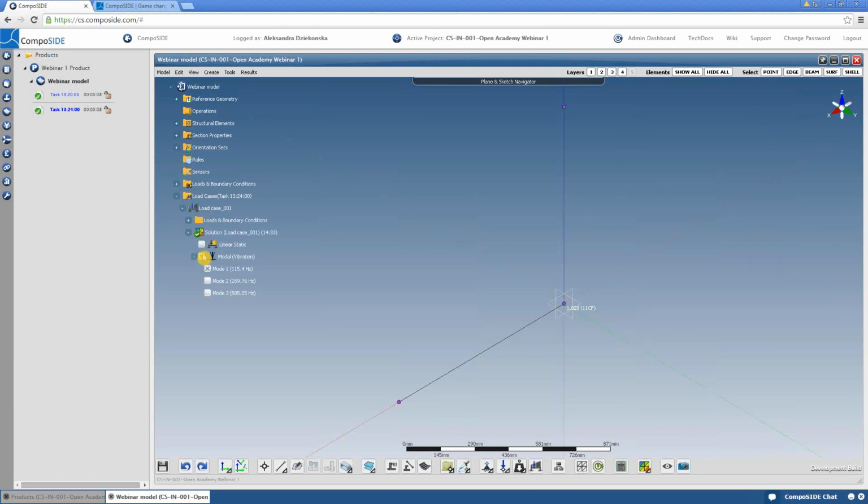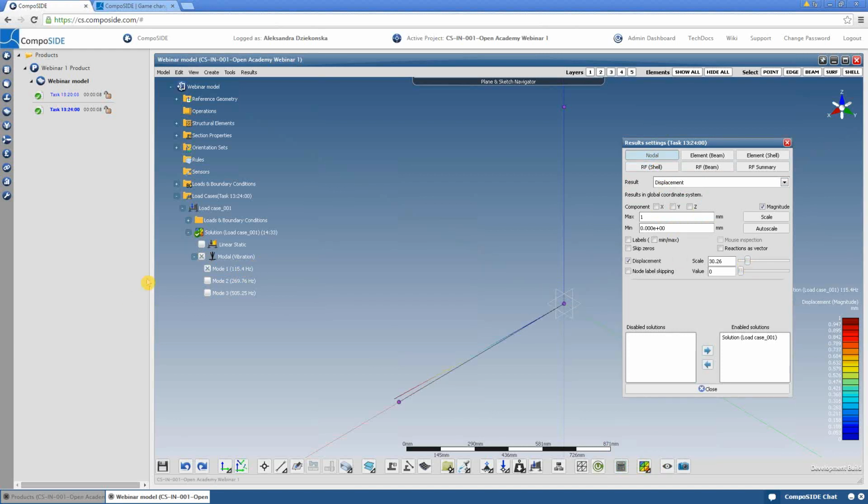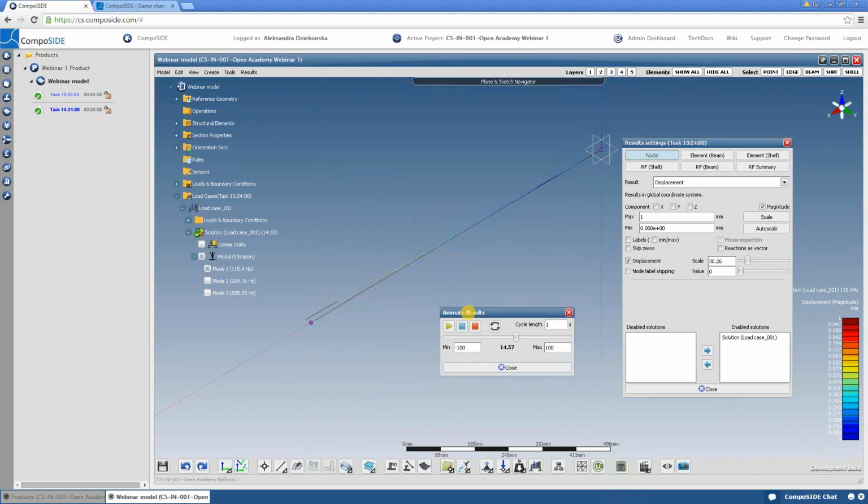Now let's check whether we are meeting another brief, the stiffness brief, which was the frequency requirement. We had 100 Hertz. You can see that the first mode is 115 Hertz for this particular beam, and Ola is going to show us the visualization. We can see that it's a sideways vibration of the beam, and it meets our criteria. Okay, let's go back to the presentation.